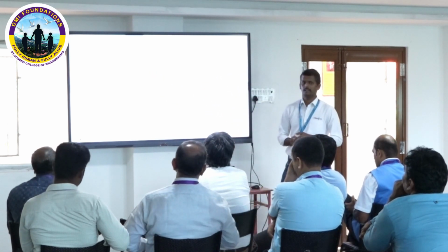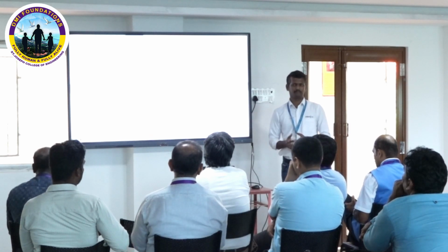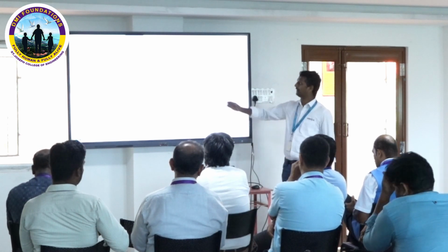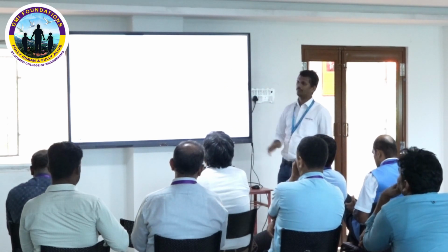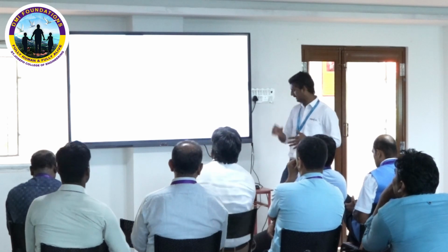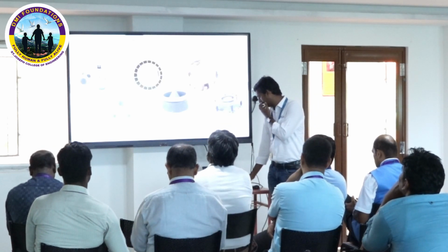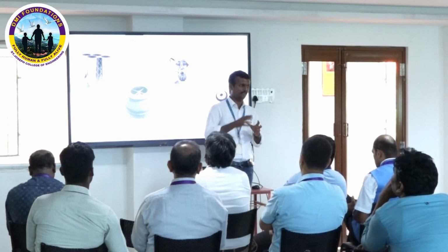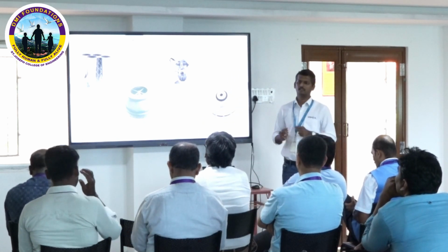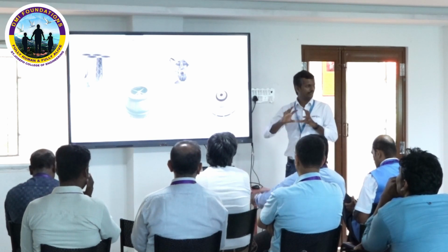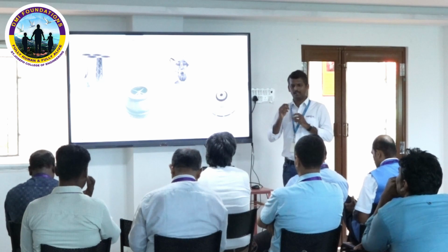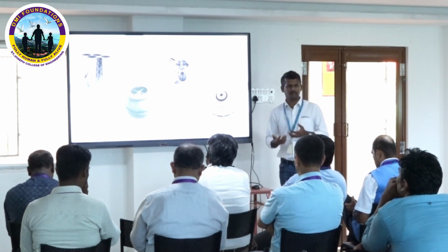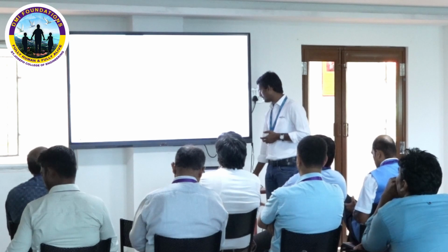Optimize the post processing, like when the component manufacturing process is very huge. If you want to optimize it, then we can go for AM. Improve functional performance. In the GZ19 satellite component which I showed you, initially it had around 12 components, and these 12 components were welded together. This is used for radio signal transmission. Now when you have a weld, the performance of the radio signal reduces. So if you want to improve functional performance, then you have to go for additive manufacturing.